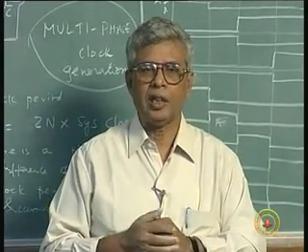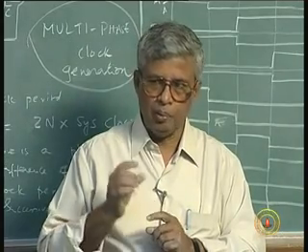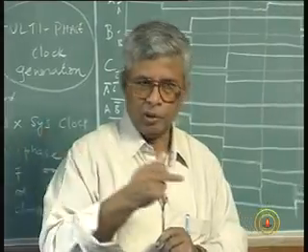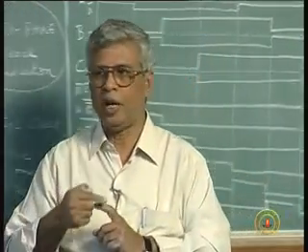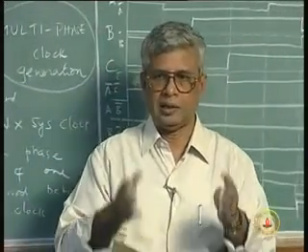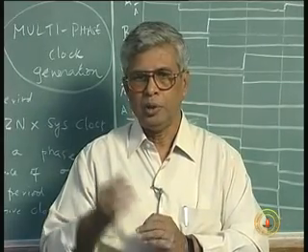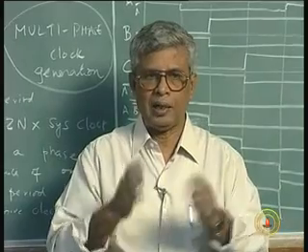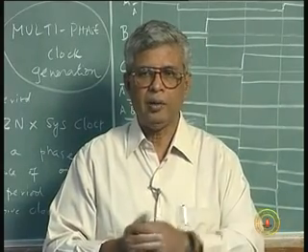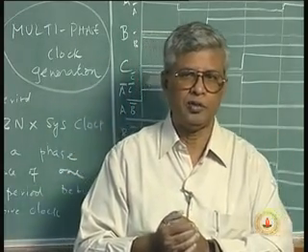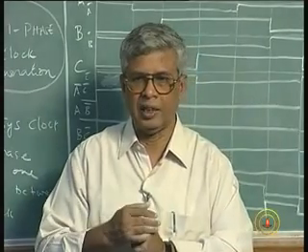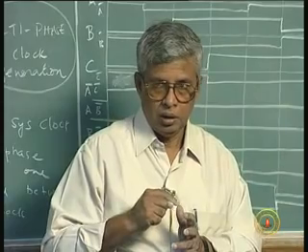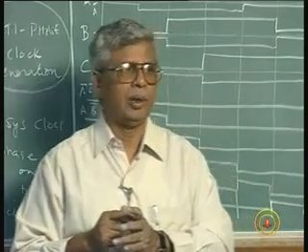The other two applications we saw the other day were the parallel to serial converter and the serial to parallel converter. Supposing serial data is coming, I gave you examples of data coming through telephone lines in bit form, and you want to assemble it as words, that is serial to parallel conversion. Or you have computer generated data which is available as parallel data, bytes or words, and you want to transmit it through your telephone line. You have to shift it serially and send it. So the other applications are the parallel to serial converter and the serial to parallel converter.